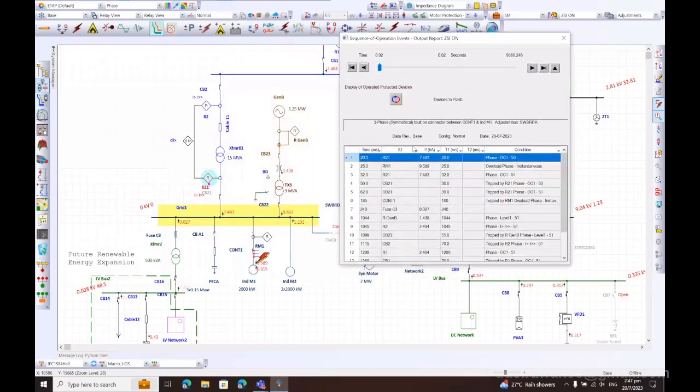This calculates the fault current all the way to the motor terminal, and you can see graphically which protective device responds based on the fault location. So in this case, it tells us if I have a fault at the motor terminal, the incomer breaker is going to trip first based on this sequence.